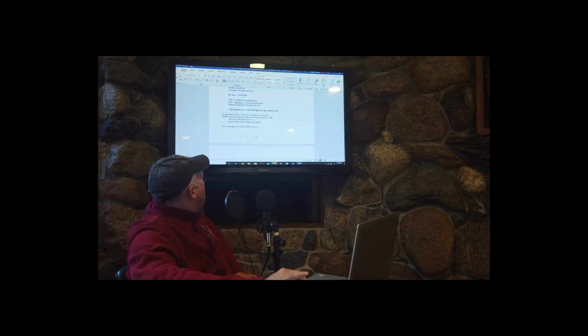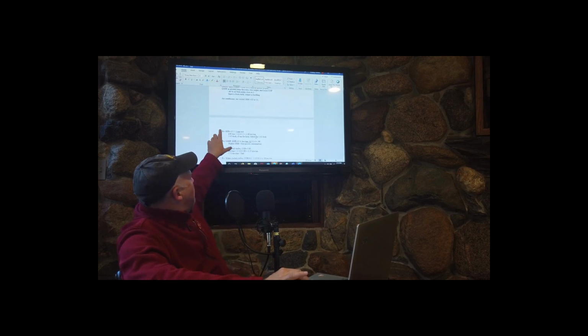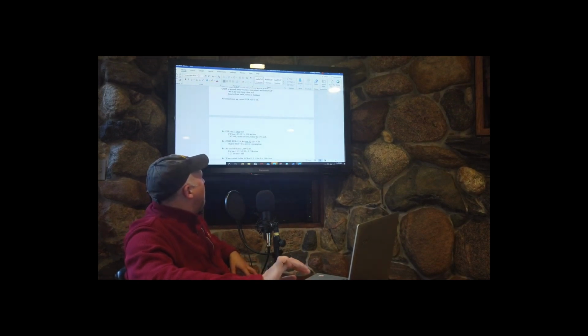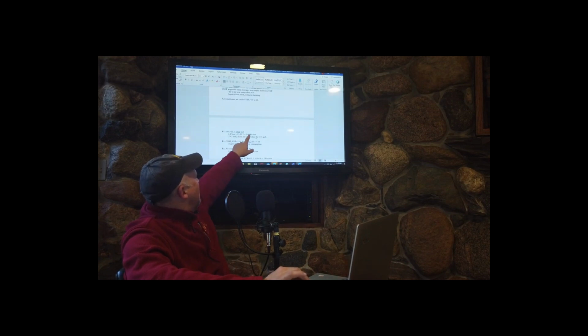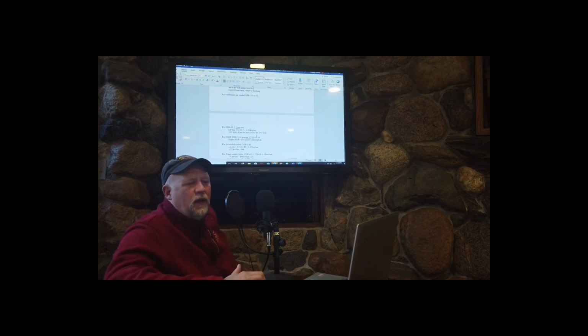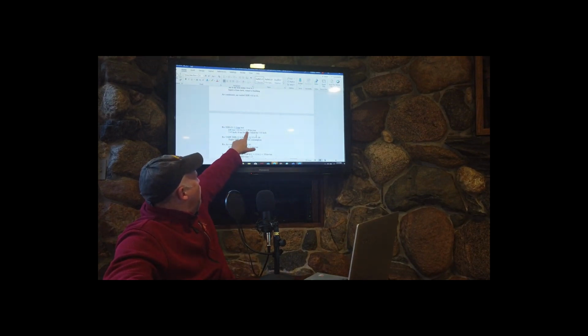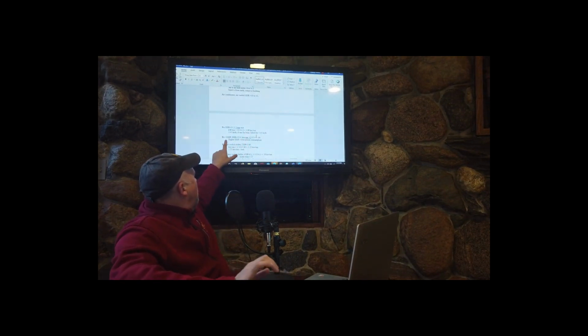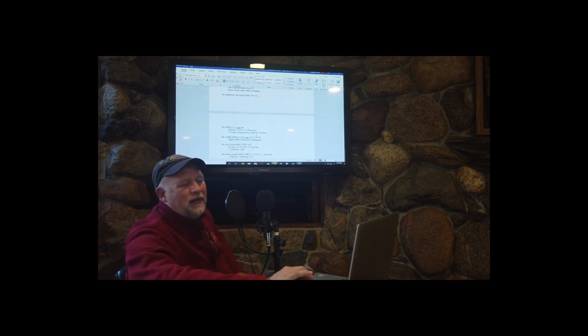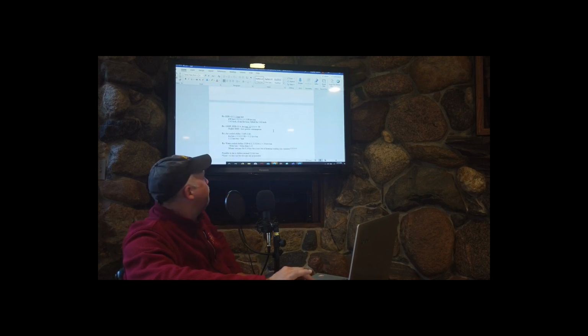All right. Let's see here. Some examples here. So I broke this down for you to give you some examples of different types of cooling equipment and what some standard kilowatts per ton are. This first one is a kW per ton of 1.09. Think of this as a really good residential split system with that condenser outside. That might be 1.09 kW per ton. For a ground source heat pump, though, you might be able to get that down to 0.9 kW per ton. A little bit better. Pretty good.